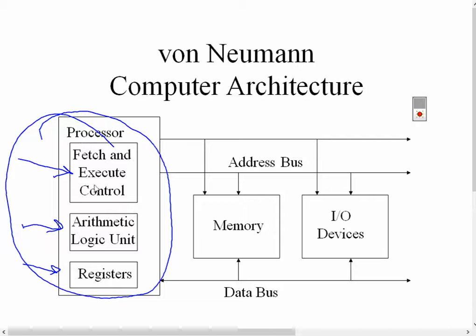Basically the whole notion behind the control unit is that I have to have a way of coordinating what happens when. So the role of the control unit is that it keeps the clock. It's that element that has the clock that's ticking, and that clock drives the program counter, and the program counter is the thing that is defining which instruction we're going to execute next. So this is a very important part. We're going to look at exactly how this works in just a bit.